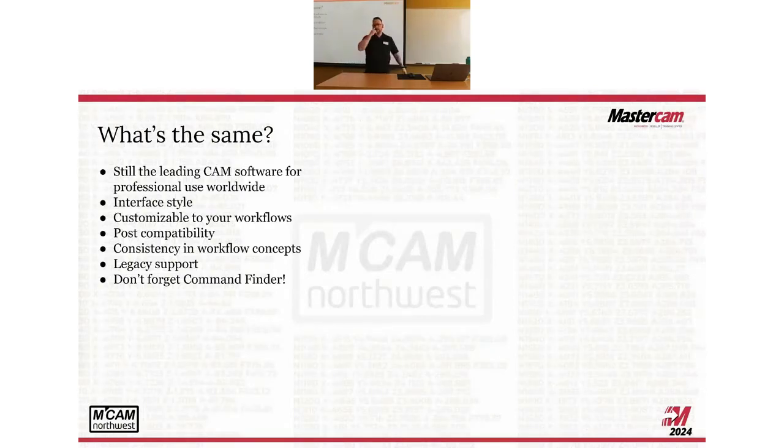Oh, and don't forget, Command Finder. It's a fantastic little tool. On the Home tab, far right-hand side is Command Finder. You can click that, you can type in whatever you want, and it will find that command for you. So even if you don't know the interface, that's a quick way to at least get going while you're learning.